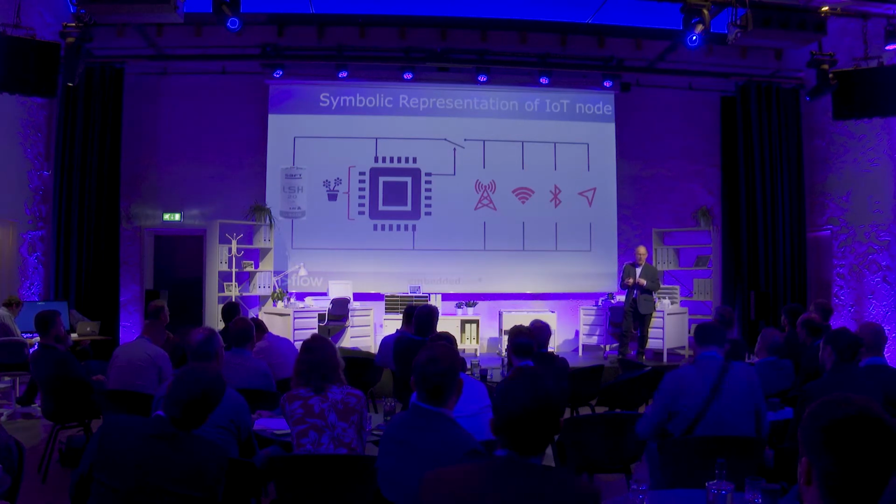So we might be talking 200 milliamps, maybe a peak current of an amp in some of those radios. Bluetooth, much, much, much lower, in fact. But we've got a power challenge to meet. And of course, as you know, we're meeting that challenge just by switching the power on and off to the radio modules.